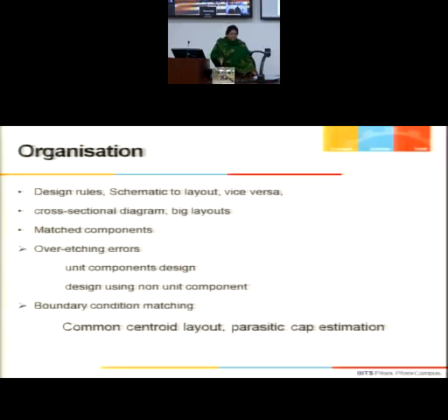It is moving beneath the gate oxide also, so that the total length is changing from the mask length. All these deviations are known as process variations. These are because of the inherent nature of the chemical processes, which we cannot control.